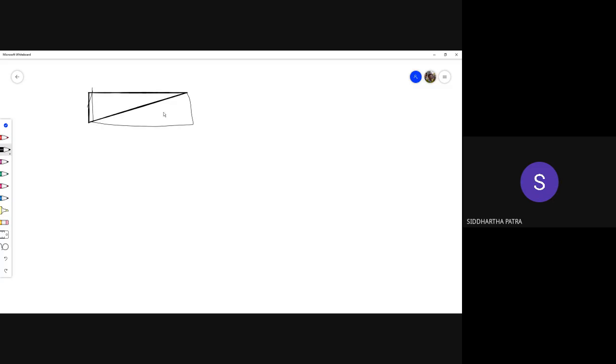Imagine if I divide a cantilever beam with two CST elements. I'm applying 100 Newton force. The uniform thickness is 1 centimeter. This height over here is 5 centimeter, and the length over here is 1 meter. For the sake of simplicity, let's take this to be 10 centimeters.